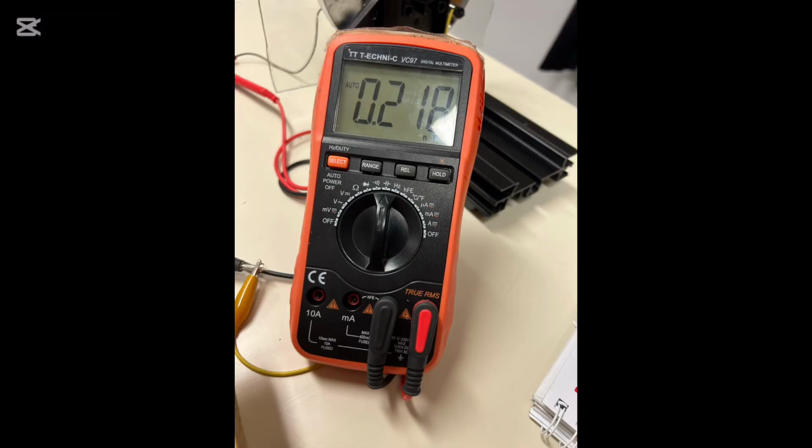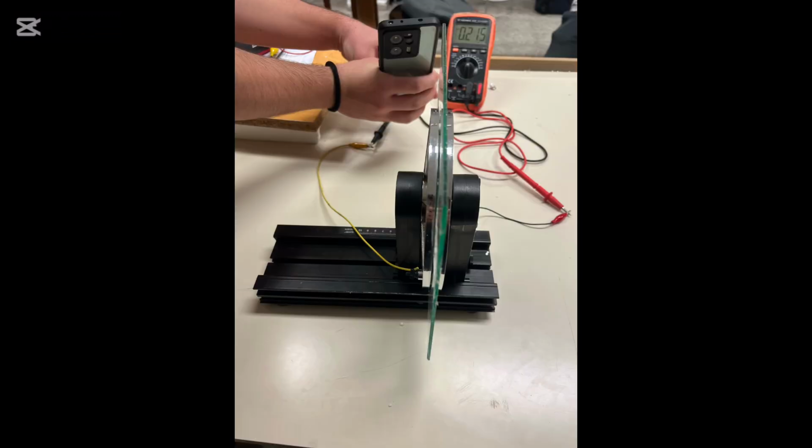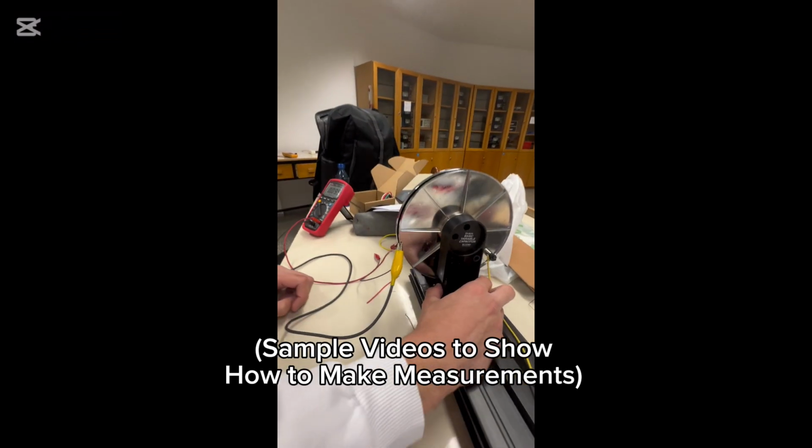To measure capacitance, we connected the plates to a high-resolution LCR meter capable of detecting values in the pico to nanofarad range. We also had a caliper for measuring plate separation and various thin dielectric sheets, wood, glass, and paper with known dielectric constants. The experiment was carried out in three parts.